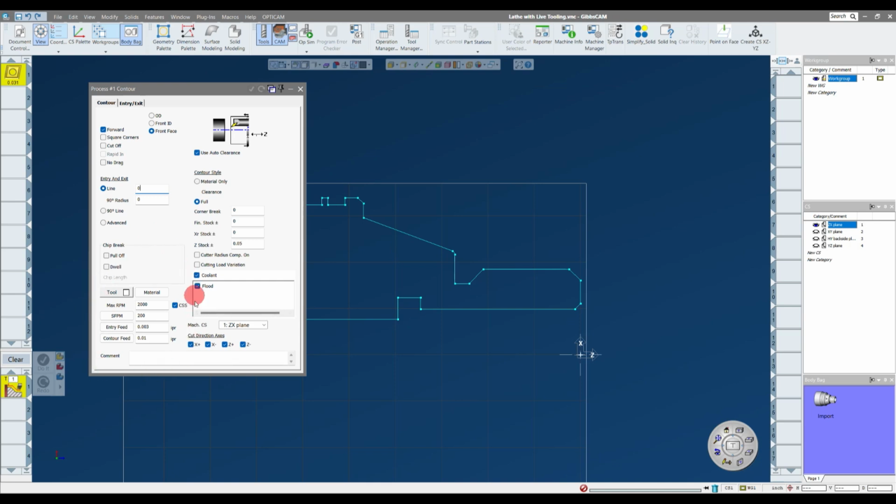I'm not going to take too much of a deep dive into the cutting parameters. We're going to be using constant surface speed mode. This is where you would set your G50 if you're running a FANUC control, your max speed limit, something like 3,500. This will be your surface feet per minute. And again, if you're using FANUC code, this will be your G96 constant surface speed here. Entry feed. This is the entry feed from the rapid plane. Once it gets done rapiding to my approach point, 100 thou away from the cut, it'll use this entry feed. So I usually bump that up a little bit faster, and then you get to your actual cutting.